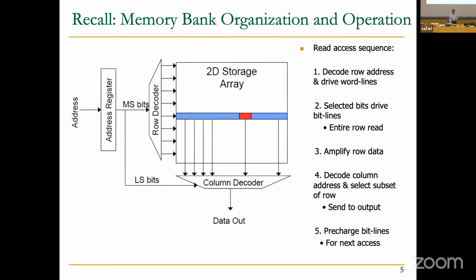But let me just wrap up memory technologies. If you recall, we said memory technologies consist of banks for multiple reasons: to reduce latency, to improve throughput. And this is a two-dimensional storage or memory array that's common to many technologies. Many technologies are organized using these storage arrays. And then if you look inside the storage array, there are smaller storage arrays. And if you look outside, we basically combine these storage arrays to get larger structures, right? So if you recall, we had rows and columns.